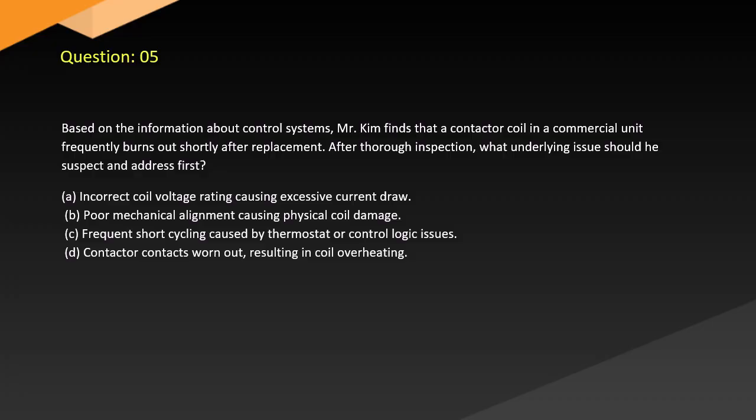Question 5. Based on the information about control systems, Mr. Kim finds that a contactor coil in a commercial unit frequently burns out shortly after replacement. After thorough inspection, what underlying issue should he suspect and address first?